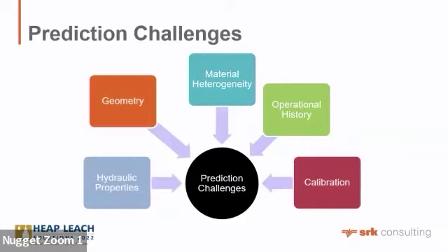Then the geometry, it's complicated in many instances. For example, you're going to see one example that is a more complex system. On-off pads are really easy; once it's off, it's off. Regular shaped frustums are less complicated. But in many instances, heap leach operations are valley fill, so in that case geometry is quite complicated. Also, it's built in different lifts and different phases. The heap leach pile is expanded, because very few of them actually look like what was originally designed.